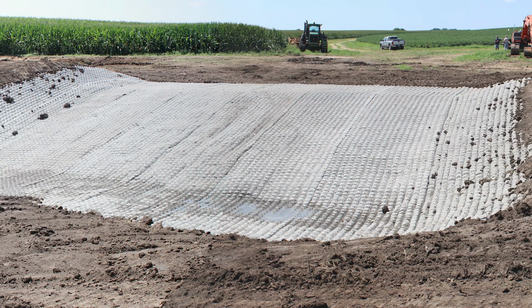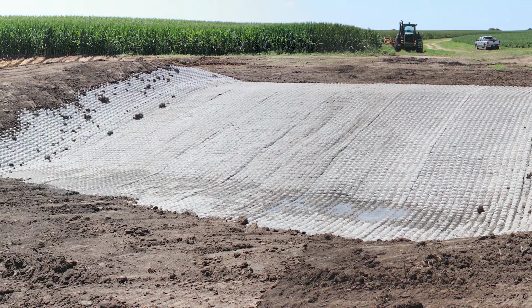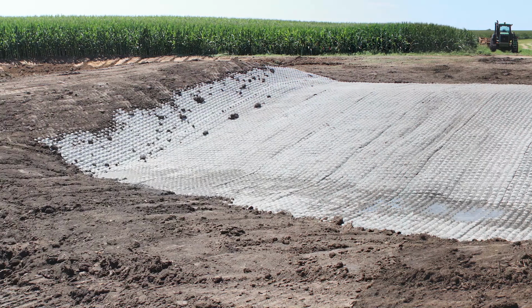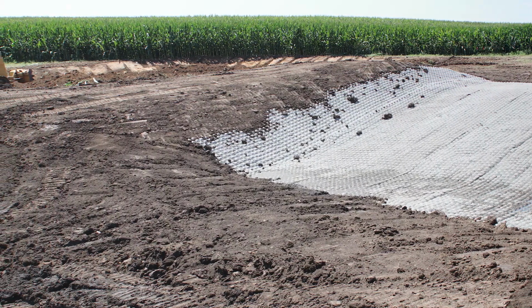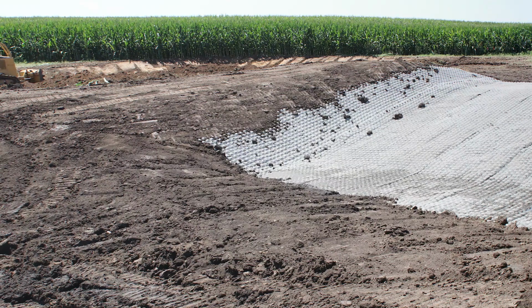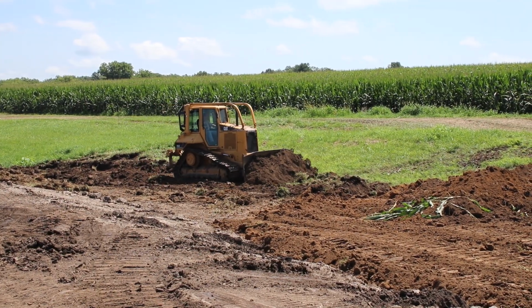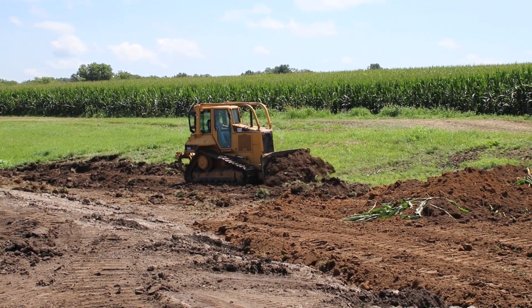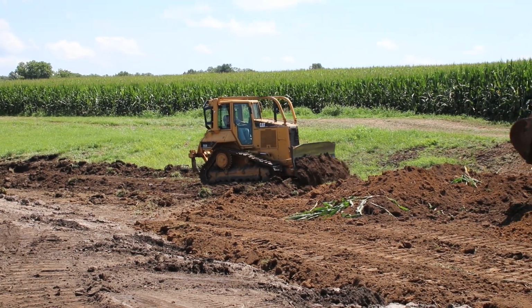If you remember, this chute was designed to handle about a 5-inch rain over a 24-hour period. There will be times when this area receives more than a 5-inch rainfall event, and we do not want the runoff to damage the structure, so we designed a low point or overflow area off to the side to handle those infrequent but high flows. This low area works to prevent the berms from being overtopped by water during large storm events, which could easily cause erosion and eventual structure failure.